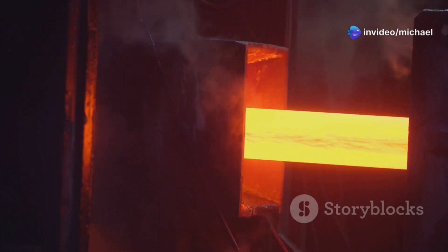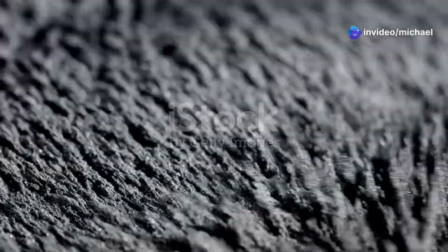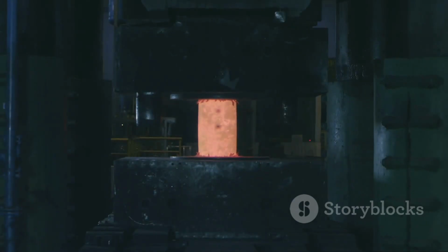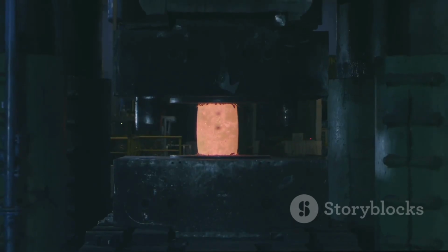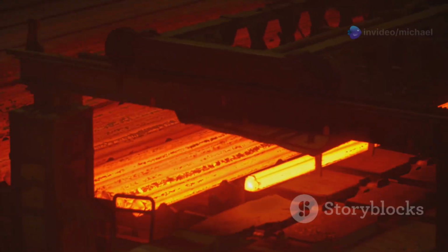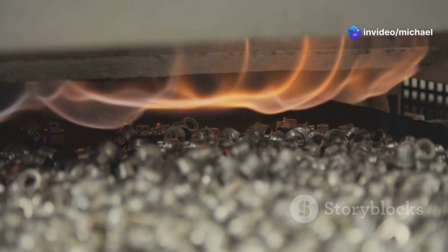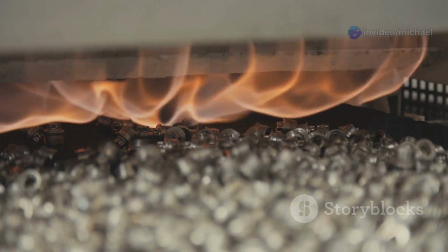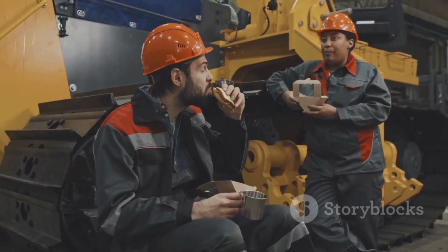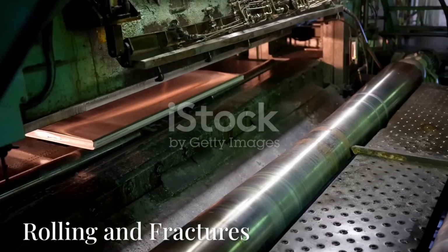One important process is called annealing. Imagine metal as a bunch of tiny metal grains all stuck together. Working the metal can make these grains squished and stressed out. Annealing is like giving the metal a relaxing spa day. We heat the metal up and then let it cool down slowly. This lets the metal grains relax and rearrange, making the metal less stressed and less likely to crack. It's like taking a break when you're working hard. It helps you come back stronger.